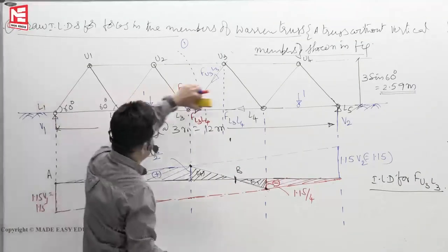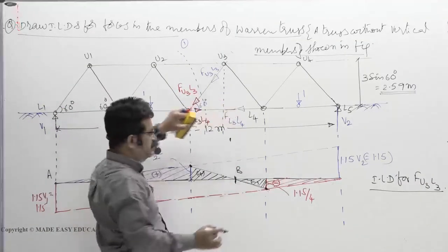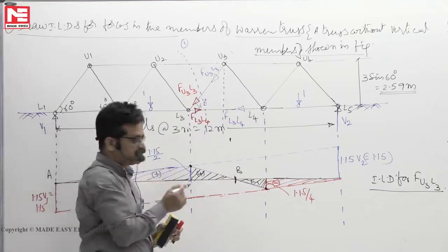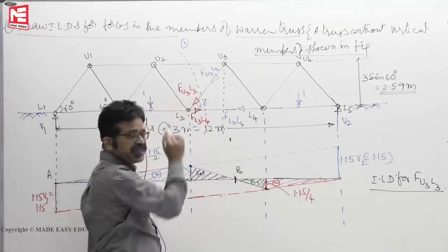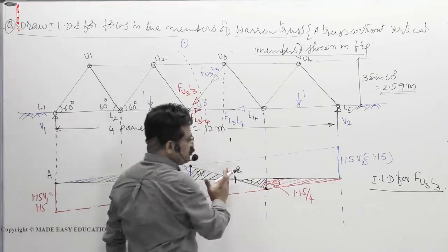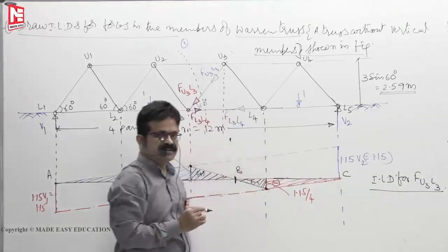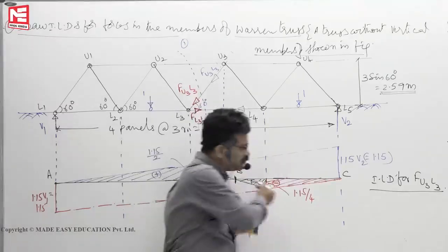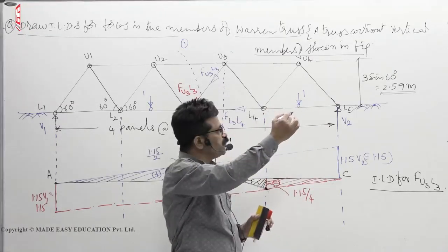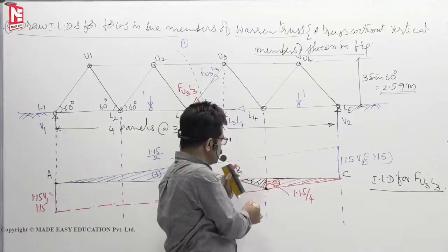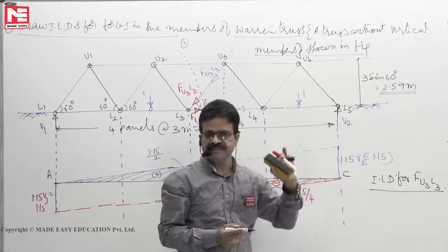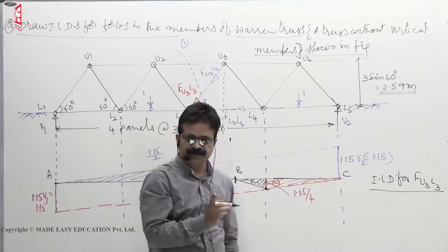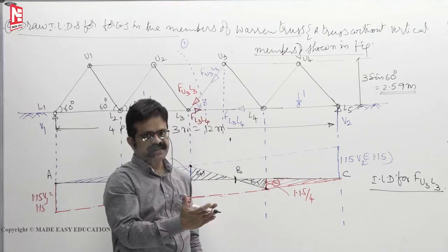That live load you have the choice to move up, forward, backward. If the live load is on the span AB, wherever it cuts the horizontal line, then you will get maximum tensile force. If the live load is between BC, let us say, then you will get maximum compressive force. That means live load should not be here and the engine should go beyond the support and from the last compartment onwards it should be there like this. Dead load always we have to keep in full length. Live load you have the choice.